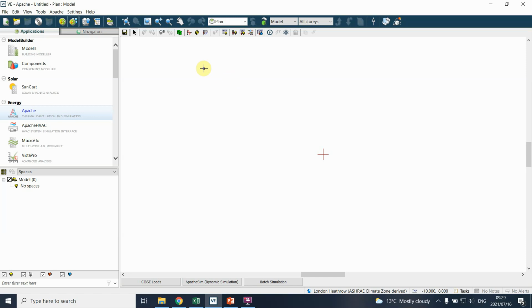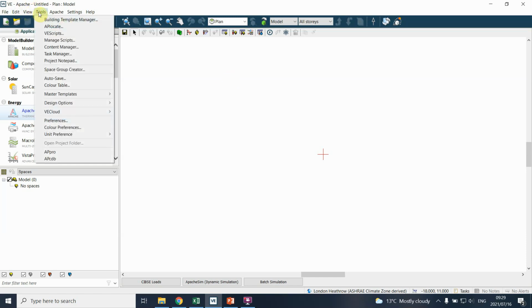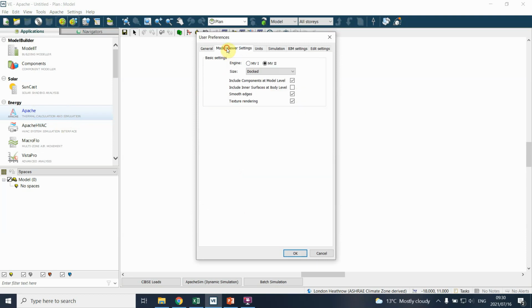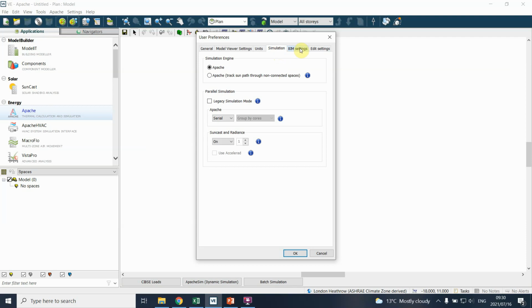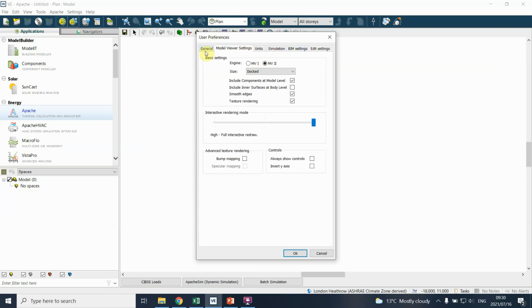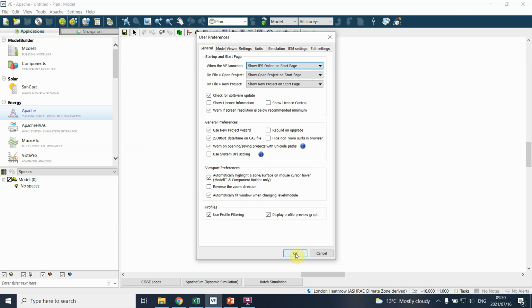I think one last aspect that you can do, as you've now opened it, before we stop the video, is you can go to preferences, and it's important to check there that your units are actually correct. You can choose between imperial or metric, and the rest of it should be in place and should be correct for you. So you don't need to change anything there yet.